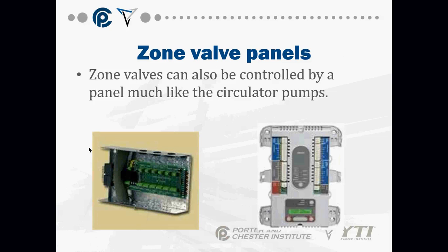And there are your zone panels. Your zone valves can be controlled by either one of those, to be quite honest with you, much like your circulators. I've put in 100 of these, either one. I like this one a lot better than that one. These are actually very easy. They're color-coded and pretty well labeled. You can manually open and close valves by going through the little program down here. With this one here, you have to jump stuff out to make stuff work. So I like this one a little bit more.